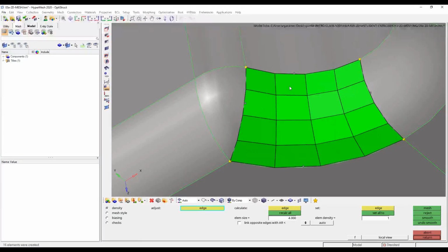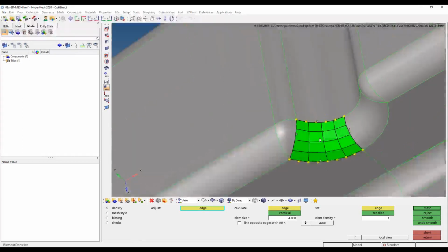The area that needs to be covered by squares hasn't changed, just the number of squares. So as a result, the elements need to get larger if I'm going to choose to use fewer of them. So why I bring that up is you want to be a little conservative about how much you're incrementing these edges.